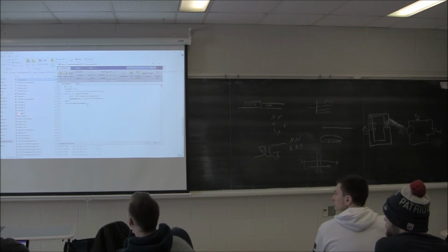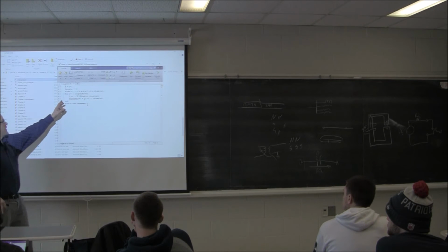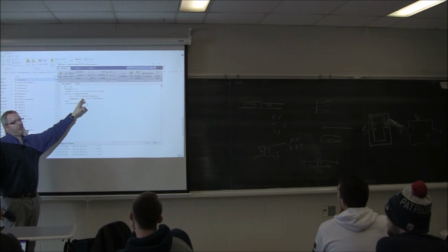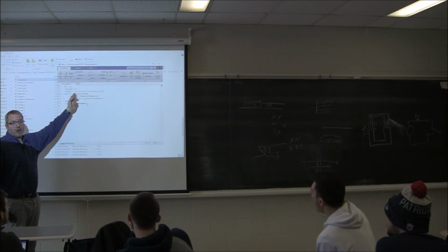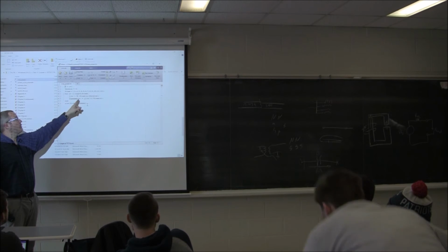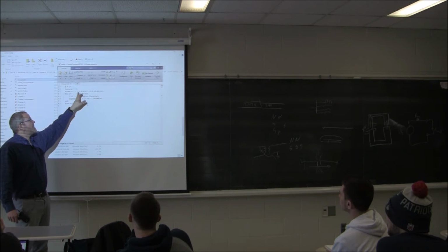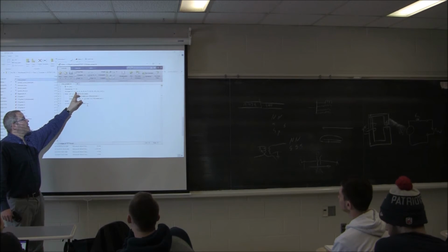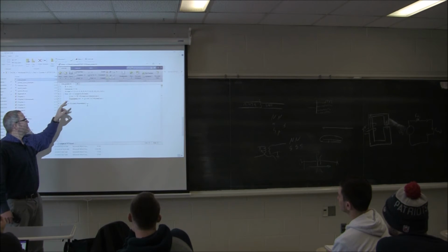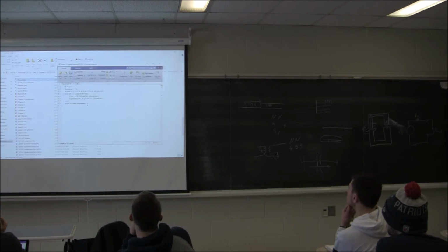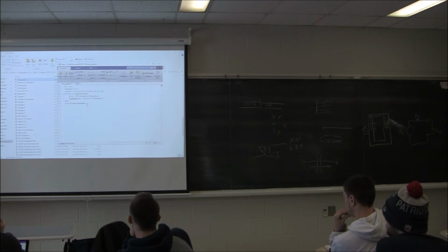So I'm trying to go ahead and just brute force it. I've got a vector called R load, which has 1 through 12. This is just a fancy way to say how many elements are in R load, because I want to run a for loop for as many elements that are here. Then I is just V over R. And I'm indexing from here by using this N. So this is position 1, 2, 3, just matching up the numbers. Then I'm going to put my power of my speaker, and I'm going to keep track of it by saying it's I squared N times R. I'm going to run through that for loop, and then I'm going to plot it. Does this syntax look different? Have you done for loops and while loops?